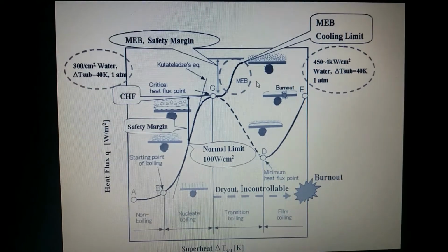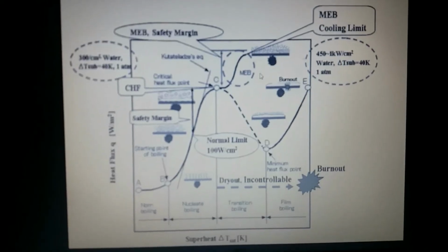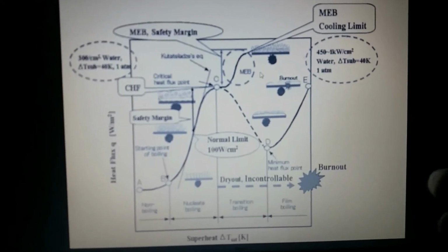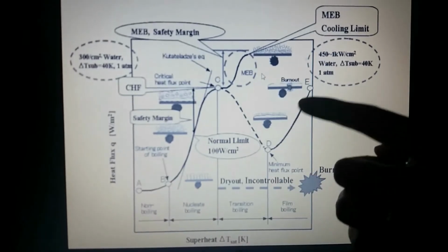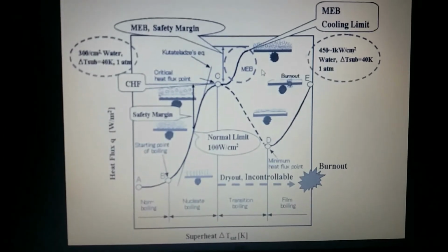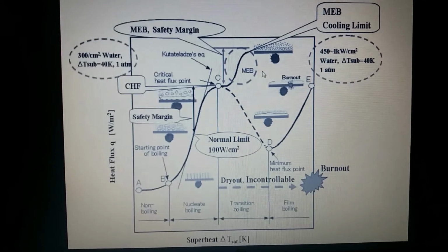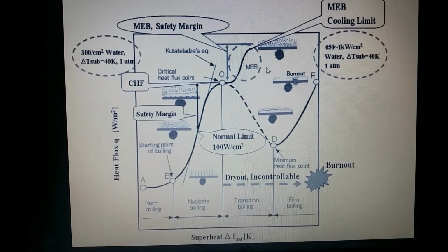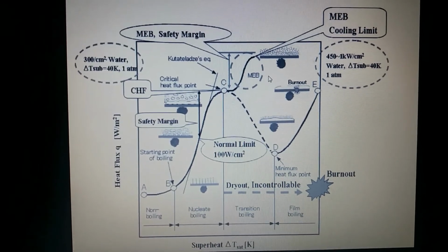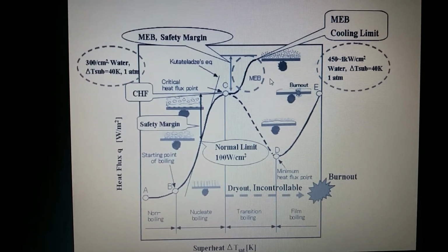Finally, the surface is seriously damaged by the high temperature burnout. That will take place here. Generally, it is impossible to control the transition boiling, so it has been difficult to apply boiling heat transfer to the cooling technology in electronics.